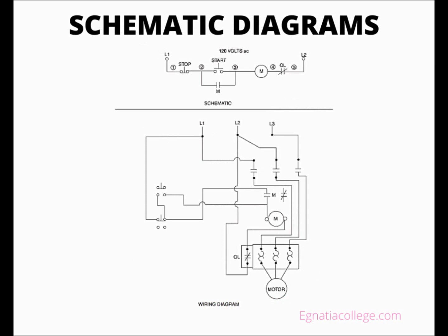Schematic diagrams. A schematic wiring diagram is a drawing that uses symbols and lines to show how the parts of an electrical assembly or unit are connected. A schematic does not necessarily show where parts are actually located, but it does explain how to make electrical connections. Several of the schematics with the school edition show connections to wires labeled G, N, and H. These stand for ground, neutral, and hot.